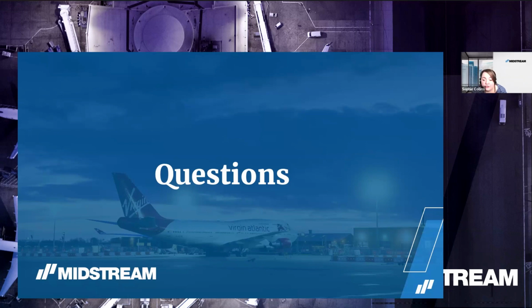Someone asks, should you calculate the maintenance factor for each and every area in the project, or can you consider a maintenance factor holistically? Well, generally, yeah, you do consider it for one entire airport. You would use a different maintenance factor if you have a particularly different area, but I don't think in aviation that is really applicable. In a port, for example, where you have containers, you will have a certain maintenance factor. Then you have an area where you move material in bulk, and you have big piles of dust lifting up. For that specific area, you could specify a different maintenance factor. But for aviation, no, it's generally just the entire airport.